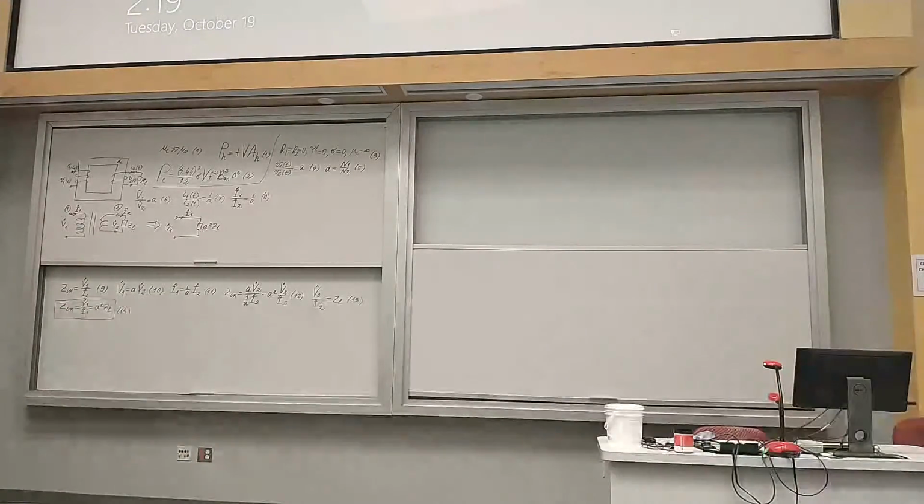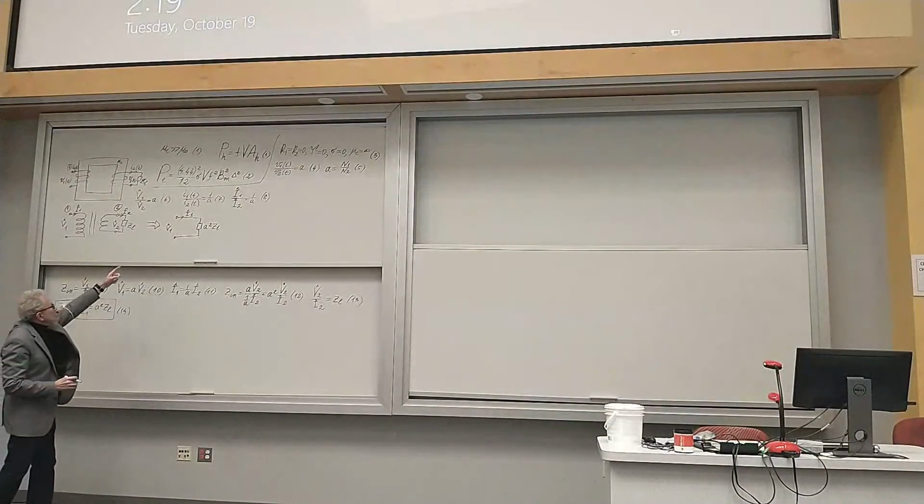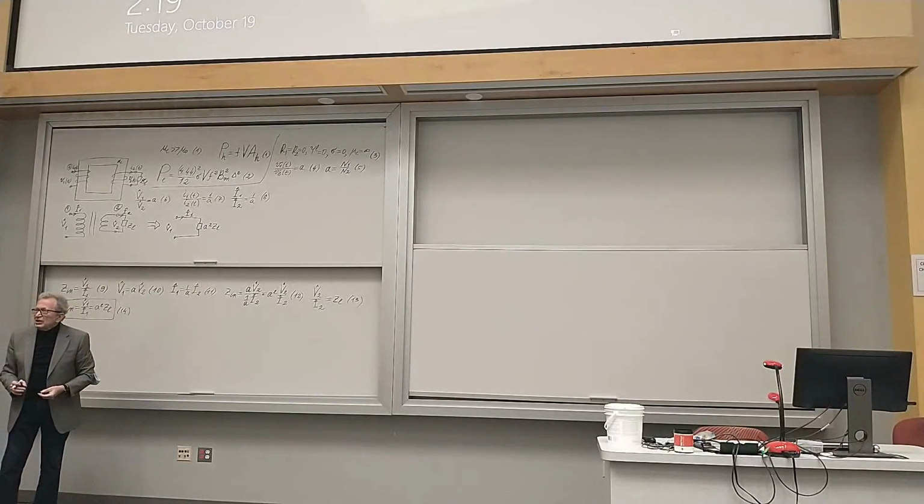It preserves the relationship between the primary voltage and primary current. And if you connect the actual ideal transformer, or this equivalent circuit, to the power network, the rest of the power network will see no difference. Why? Because it will be described by the same equations. It will be the equation for the power network and an additional equation between the input voltage and input current of the transformer, and they are the same for the ideal transformer and for this circuit. In this sense, it is equivalent.